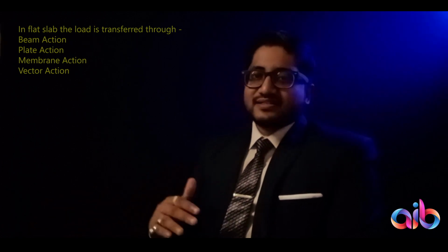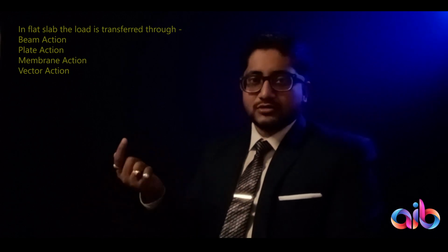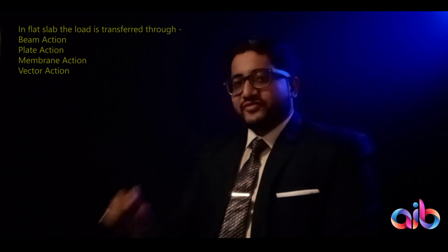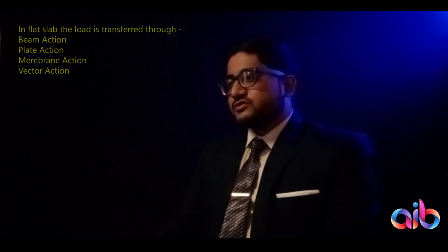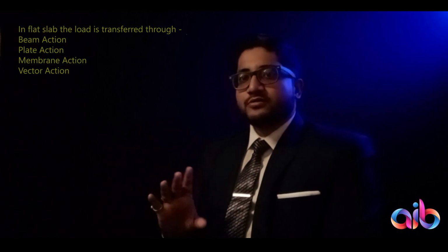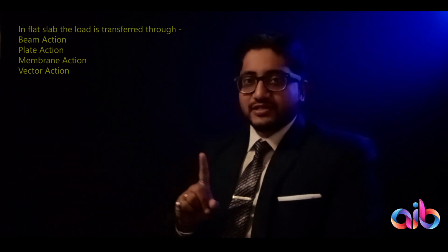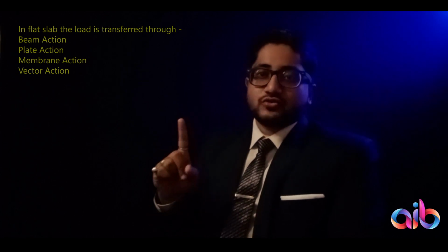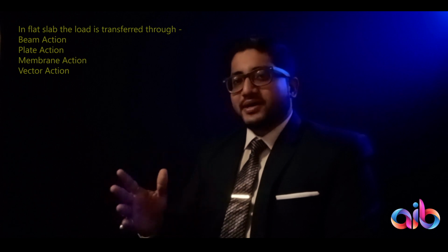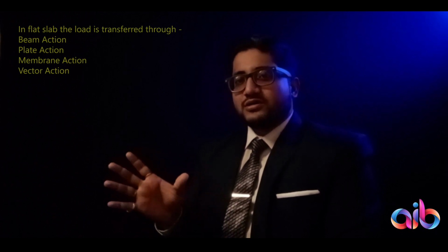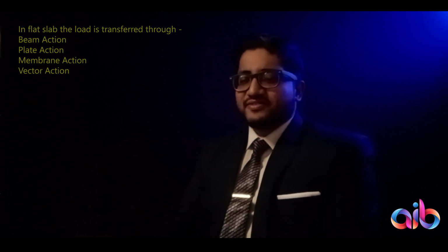Anyways, why do we have a flat slab? Let's say you have a piece of paper and you want to put it into the punching machine to make 2 holes. So with flat slabs, if you have a very thin slab and longer spans, a lot of load is imposed on the slab. So you have a flat slab type of arrangement to allow for longer spans and to counter punching shear. Otherwise the column would tend to punch through the slab itself. So you have to counter punching shear and also provide for longer spans, so you go for a flat slab with or without column heads, so that's a separate discussion.